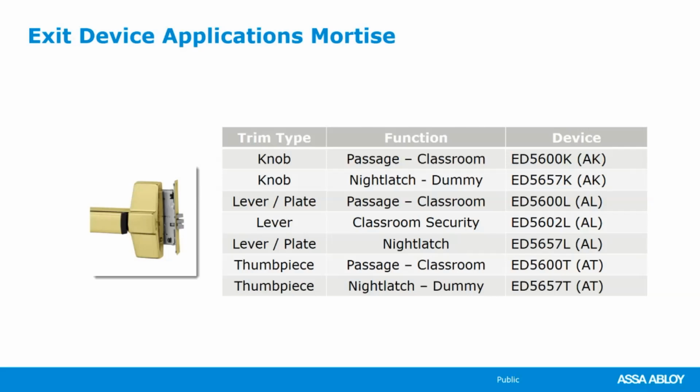Can you use 2 Mortise devices on a pair of doors? Not that I'm aware of. On a true paired opening, no. Even with a removable mullion, you really couldn't strike in against those that way. I've never seen that done. It's not designed for that. So you would have 2 single doors beside each other with a fixed hollow metal mullion in the middle. That would be part of the construction of the window wall. That could be done, but in a normal application, no.